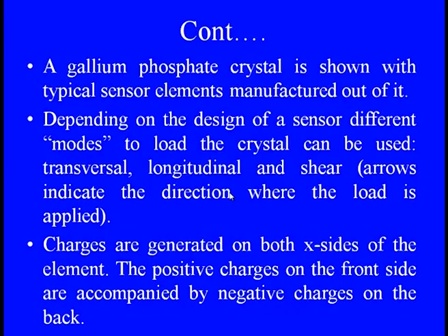the crystal can be loaded as transversal, longitudinal or shear according to the direction of the applied forces, and the charges are generated straightaway on both sides of the x-axis element, and the positive charge on the front side is accompanied by the negative charges on the back side. So there is a clear voltage change when these mechanical inputs are provided in any direction, transverse, longitudinal or shear.